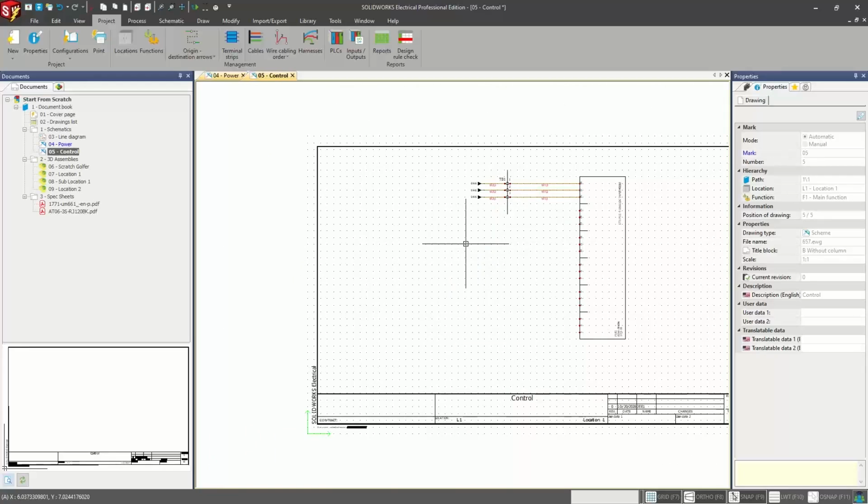The way I like to describe how the wires and the cables work, I can draw all my wires out. You don't have to all the time, but maybe I have an Ethernet line. There's 8 wires, right? There's the 4 twisted pairs. Well, I'm going to draw those out because in some of the instances I used to work with, I used to have to bifurcate those or maybe open that up and 2 pair went one way and 2 pair went the other way, depending on what I was using that for.